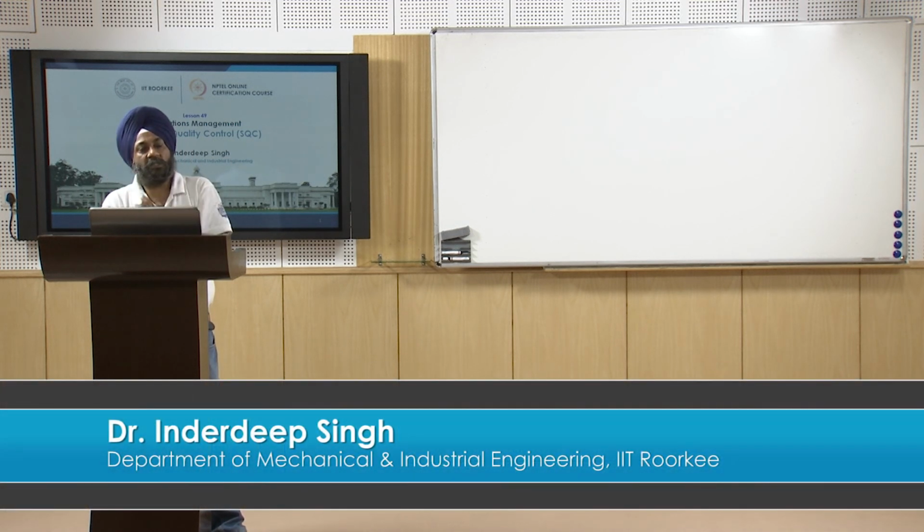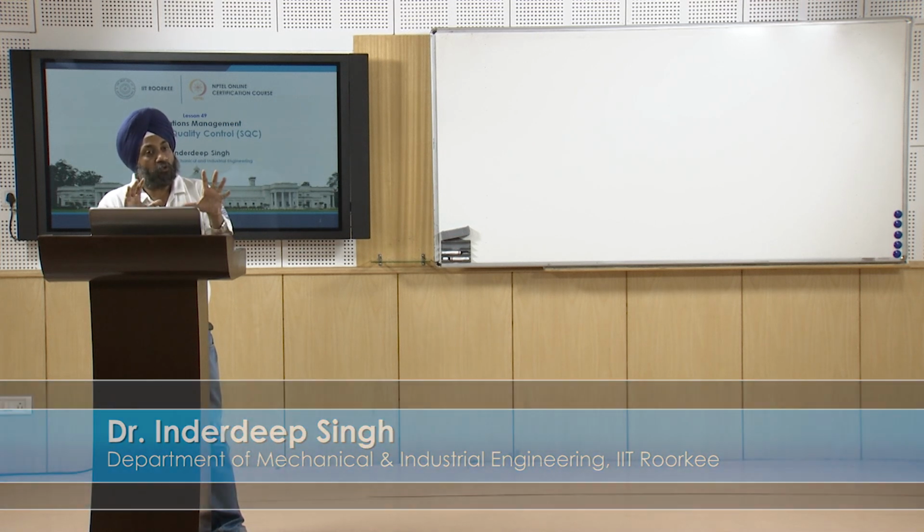So we can control the sample means within the upper and lower control limit. We can also control the range or the variability within the upper and lower control limits for the range values for each sample also. And if everything is within the control limits, we will say yes, the process is producing the products within the acceptable limits. As soon as these mean values or the range values go beyond the control limits, we will stop the process and try to check for the causes that are leading to this out of control variation in the process, thus leading to a faulty output or a poor quality product. So that is basically the concept that we exercise in order to produce good quality products.